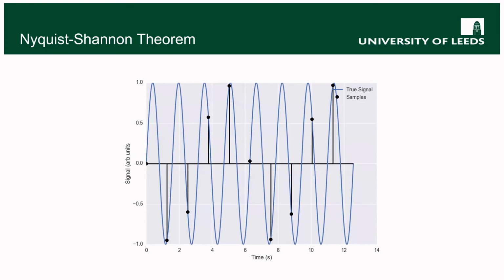So here's an example of where aliasing would be a problem. Imagine that we're not able to sample our signal particularly rapidly, and so we're only sampling at a much slower rate than the frequency we're interested in. And now we try and join the dots. Even if we assume we join the dots with a nice sine wave, you'll see that the red signal we've joined up here is at a much, much different frequency from the true signal. In fact, the signal that we reconstruct is given by the beat frequency between the signal we're measuring at and the signal that we're interested in looking at.